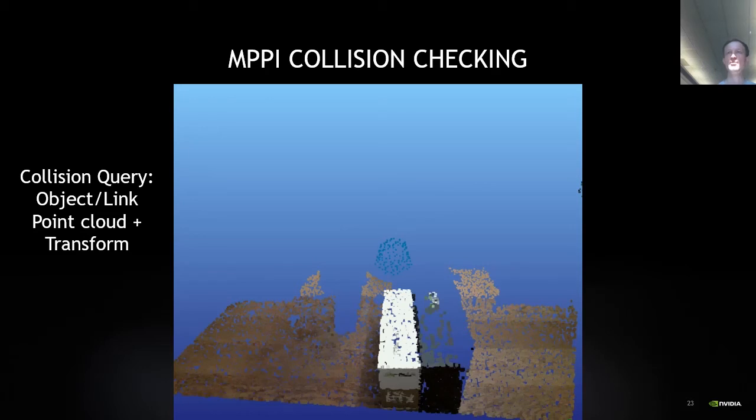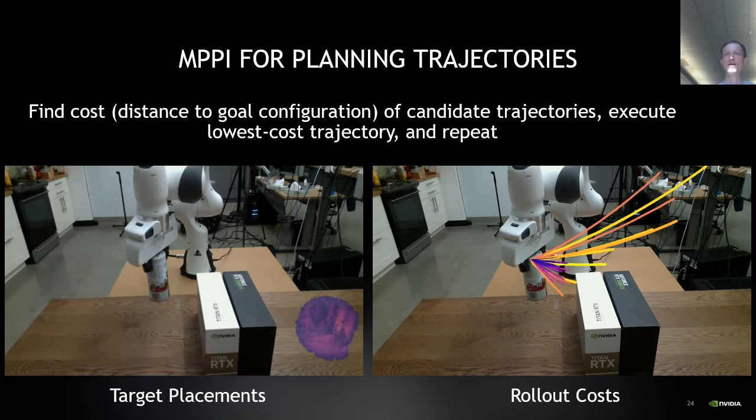Additionally, the object encodings for the robot can be cached ahead of time, so we can further speed up computation since the geometry is previously known for the robot. After trimming, the cost of each trajectory is calculated as the L2 distance in joint space to any of the goals in the goal set, and the lowest cost trajectory is executed. Note that the cost is equivalent for grasping and for placing. The only difference is the goal set configuration.